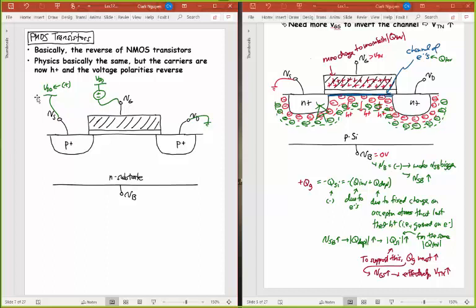I would put some VSG on VG. That's going to be less than the voltage that I have, well, the VG voltage would be less than the voltage that I have on VS in order to get this to work correctly. And VDD, again, I think you've seen some of this before too, but VDD is usually what we call our supply voltage for MOS circuits. For bipolar circuits, that'll be VCC.